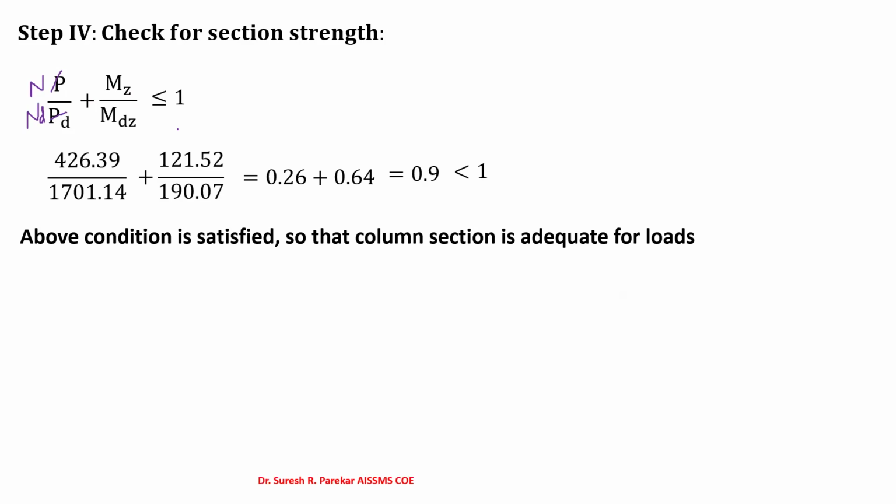Now we have to go for the design of the base. Do not go for an eccentric base, because whatever you will get from this will not be in our syllabus. So we will simply design the base plate for concentrated load only, that is axial load only. And we have PU 448.24, sorry, this is kilonewton. So M20 grade of concrete.